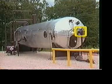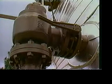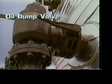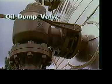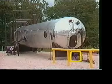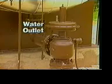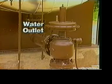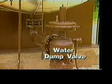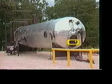Oil leaves the treater through the oil outlet, which is located near the top of the unit. The oil dump valve is located on the oil outlet line. This valve allows clean oil to leave the treater. Water leaves the unit through the water outlet, located on the bottom of the treater. On the water outlet line is the water dump valve, which allows water to leave the treater.